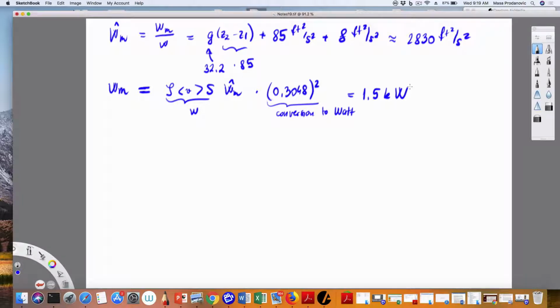So again, what was not necessarily straightforward in this chapter was coming up with these energy balances, and we didn't spend a lot of time wading through those proofs and coming up with the formula. But once you have a formula and you have these tabulated values, what you need to remember always is to check the Reynolds number. Okay? And write it down now for your exam or whatever comes up.